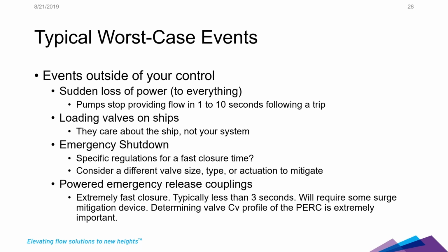Use impulse. Trip all of your pumps at once based on inertia. See what happens. Probably might not be the best response. You might not be happy with it. You might need a surge accumulator. You might need a vessel. You might need a surge tank. You might need a giant flywheel on your pumps to keep it spinning. If you lose all of your power, there's lots of different solutions for that. But it's a very real possibility. It might happen.